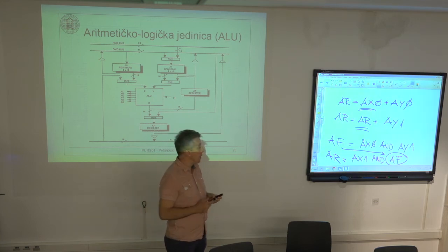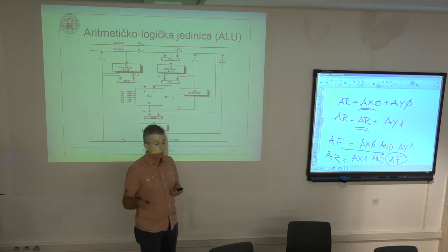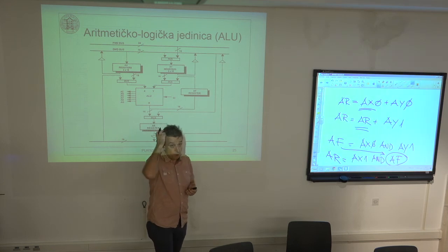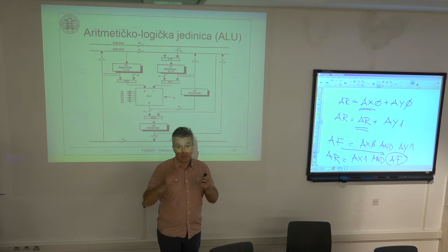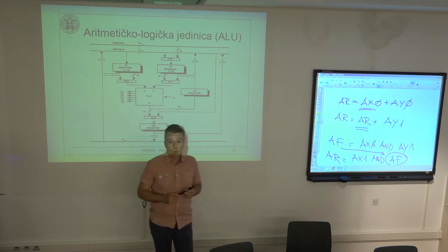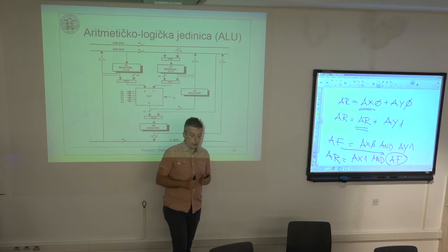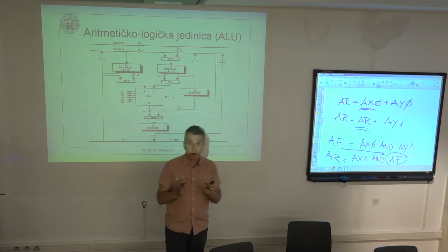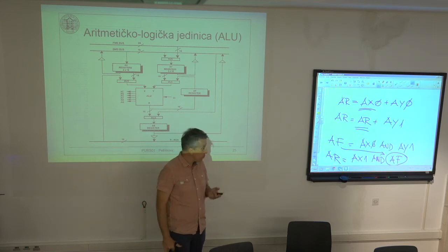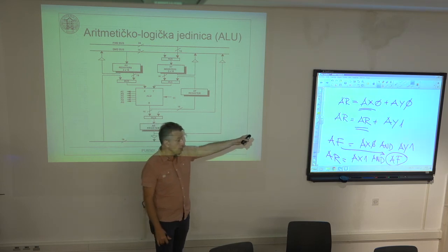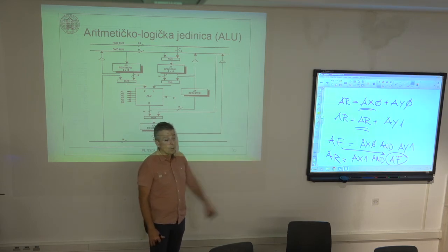So it doesn't have this mnemonic type of notation that you can usually find on typical CPUs. You have Intel mnemonics or Motorola mnemonics or whatever CPU or microcontroller you use. You first have the mnemonic of the assembly instruction, then the input arguments, and then the destination register. But all of this can also be written in this kind of algebraic form.